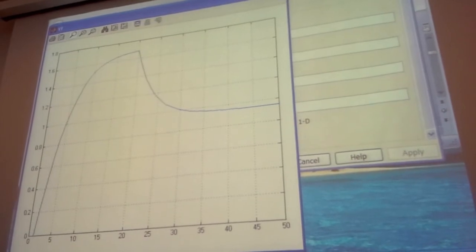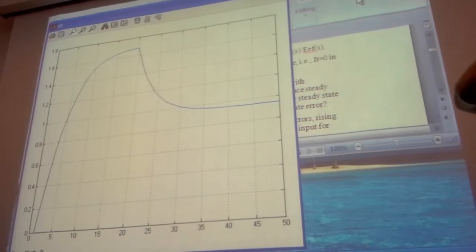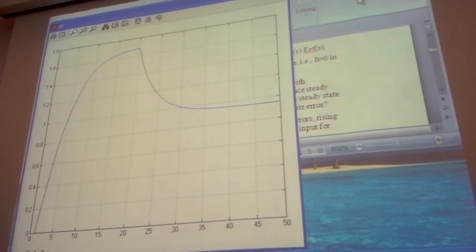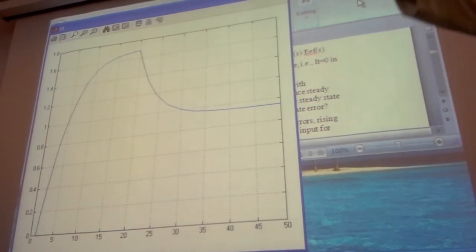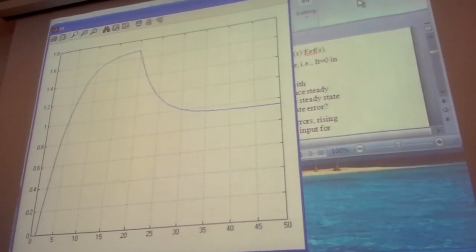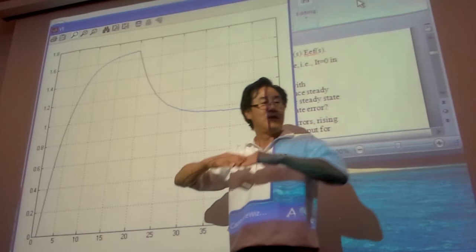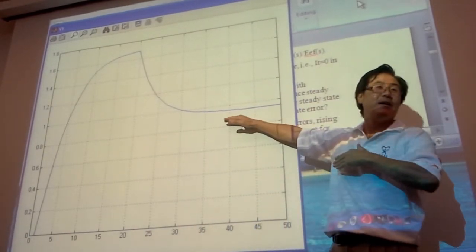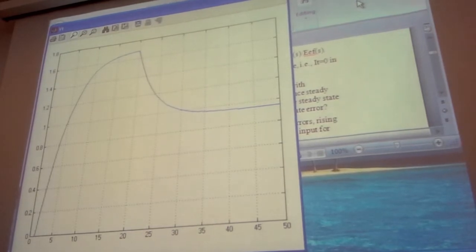Long time ago, what I mean is, first time you have a generator, the input is fixed. They don't change. So somebody used some motor, or it's a cold day, they are adding an air conditioner, whatever it is. Because load is increased, the current is increased, then voltage will drop. So long time ago, they needed to just monitor the output and increase the step input to maintain the 1. That is a manual mode. We call it the manual mode. That's what we do if we don't have a closed loop.